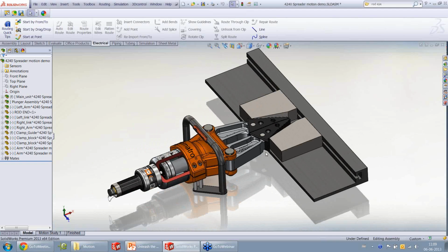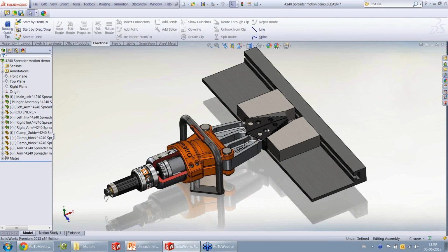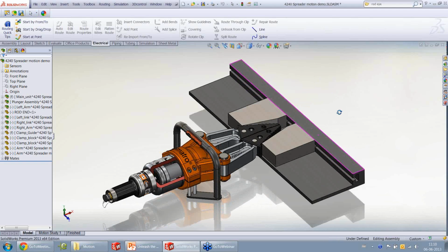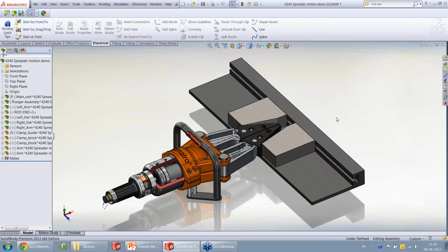Ideally, I would have to wait till the prototype is out, and then take it into the lab and create a test rig or a setup like this where I have clamps, where I'd simulate forces on these faces and try to open the jaws. So here what I'm looking at is a validation or verification. I want to make sure that these jaws can open under a load of up to 220,000 newtons or 200,000 newtons. As I said, in SolidWorks Premium you have motion analysis capabilities which will allow you to simulate motion like this.